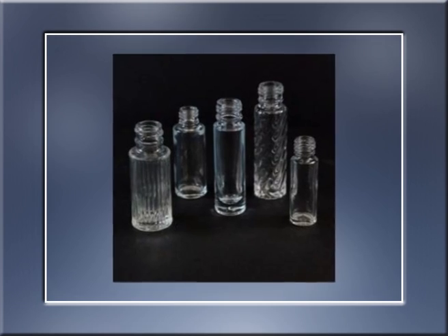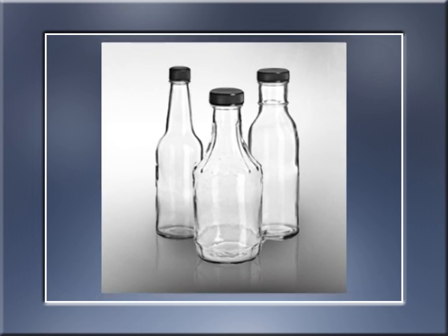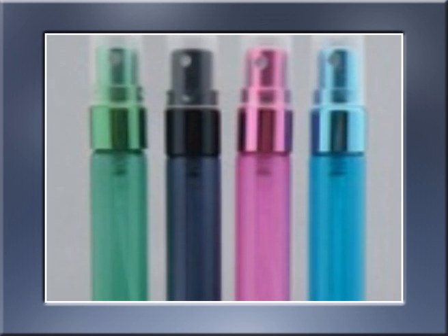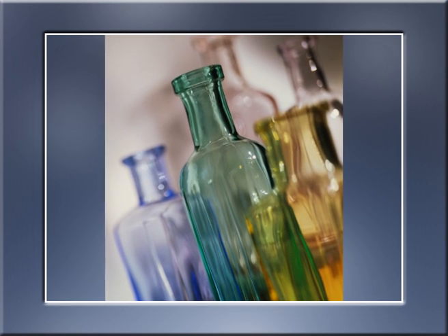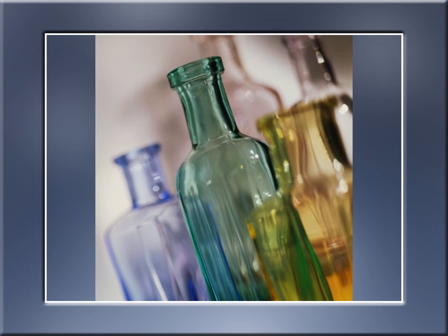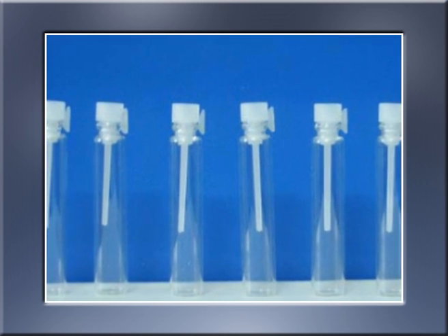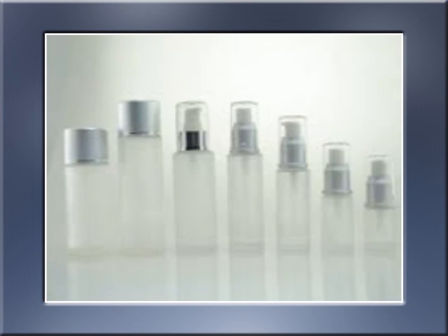The second type of material that is used is glass. Glass containers would be the preferred container for most aerosols. Glass presents fewer problems with respect to chemical compatibility with the formulation compared to metal containers and is not subject to corrosion. Glass is also more adaptive to design creativity and allows the user to view the level of contents in the container. However, glass containers must be precisely engineered to provide the maximum pressure safety and impact resistance.